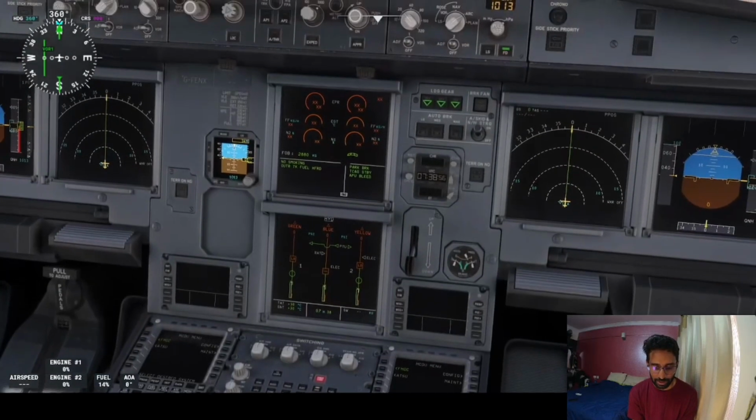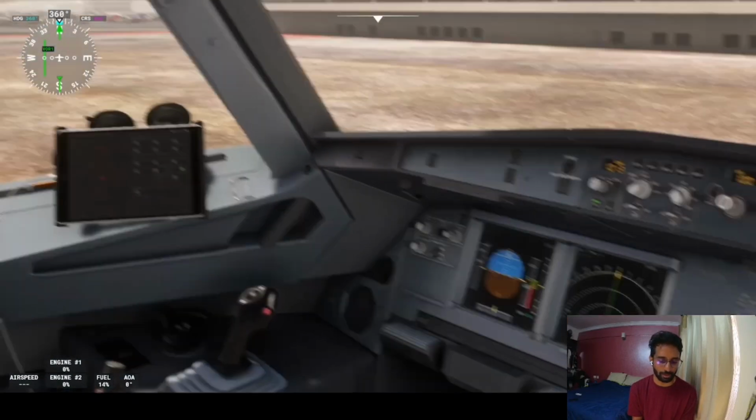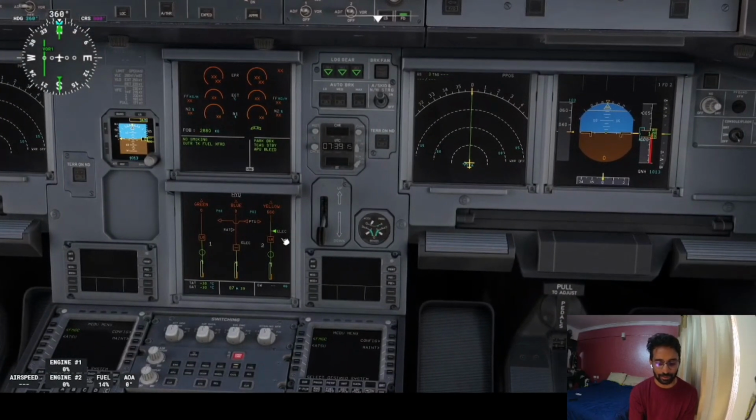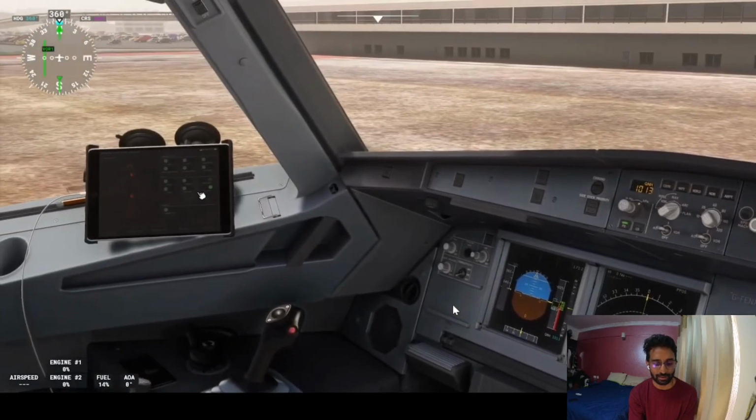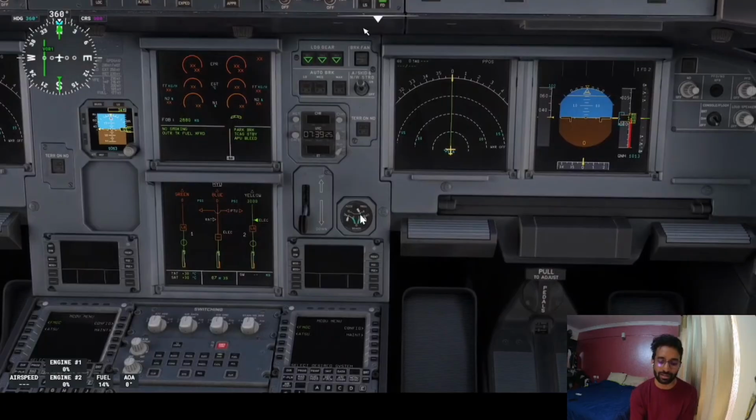Now let's see another situation. I depressurized the accumulator just to show you that low pressure situation again. Hope you are following all these things. Now the cargo doors are operating. So when the cargo doors are operating, the same thing we discussed before. See, this also pressurizes your brake accumulator. Remember, alternate braking also gets pressurized. See, when the cargo doors work, it pressurizes your accumulator also.